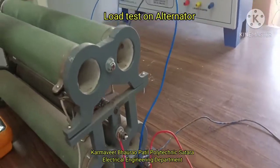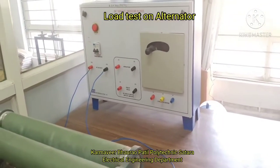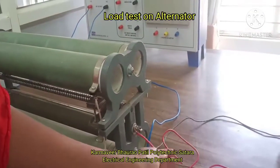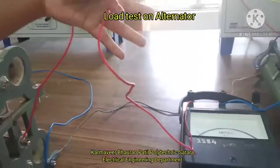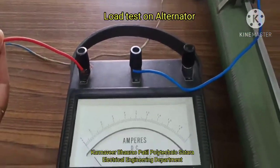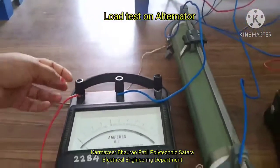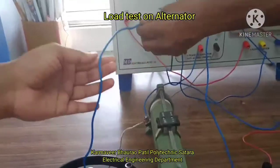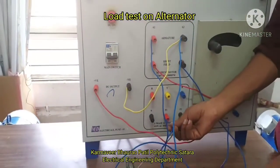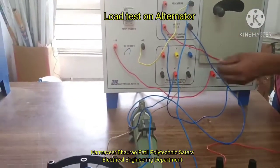So full voltage gets connected across the two fixed terminals of the rheostat, and then from the variable terminal of the rheostat we connect to the ammeter positive. This will be a DC ammeter which will measure the current through the field winding of the alternator. The second terminal of the ammeter will go to F1, that is the field winding of the alternator, and F2 will go to the negative of the rheostat.